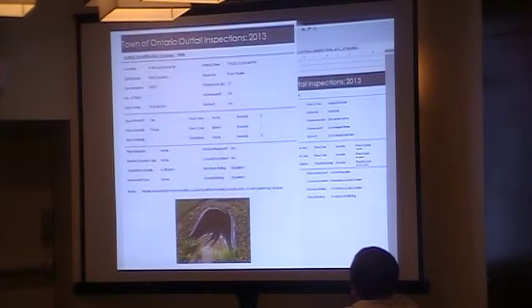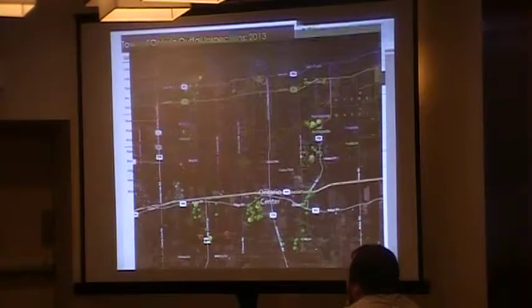So this is ESRI's report wizard. Basically just set up a little design form, and you suck in the fields from the geodatabase that we filled out. And that's the completed report that gets printed out and that we gave to the town. So you see the photo that we took, comes in down the bottom. I would mention that if you're going to use this report wizard, and if you have multiple photos, that created a real issue. Maybe eliminate one photo. If you get two or three photos, then it starts wanting to expand the report, and it really gets kind of goofy. We've got 1 minute left, so.